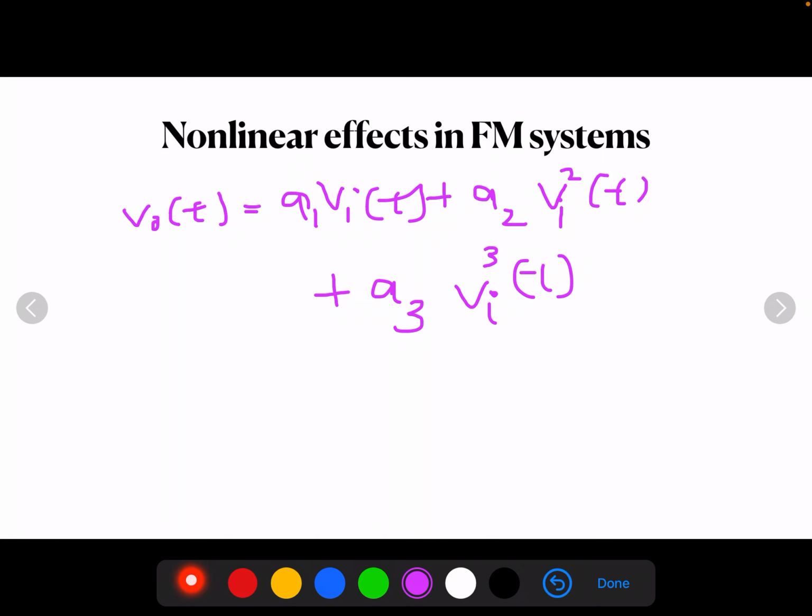So what is nonlinearity? It is present in one form or another in all electrical networks. There are basically two forms of nonlinearity. The nonlinearity is said to be strong when it is introduced intentionally, and you can control it in a specified manner, for example square law modulators, limiters, frequency multipliers, like this.